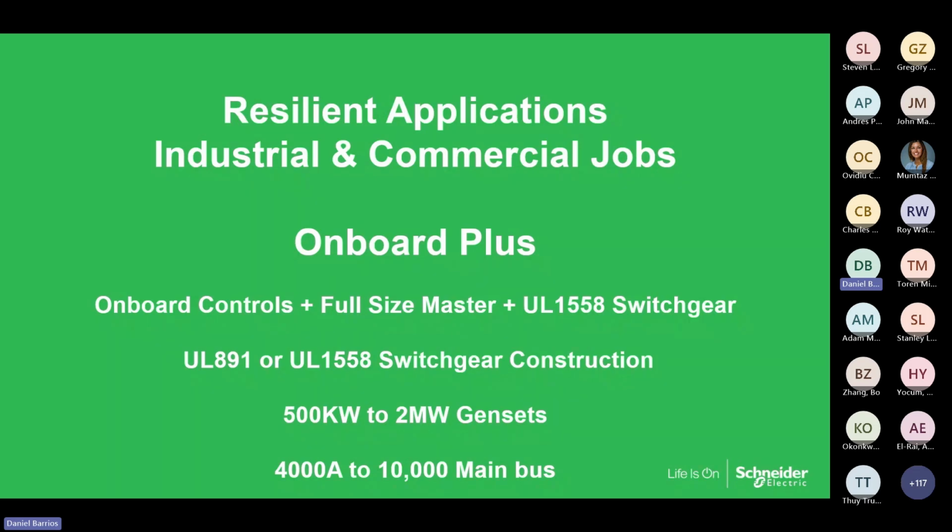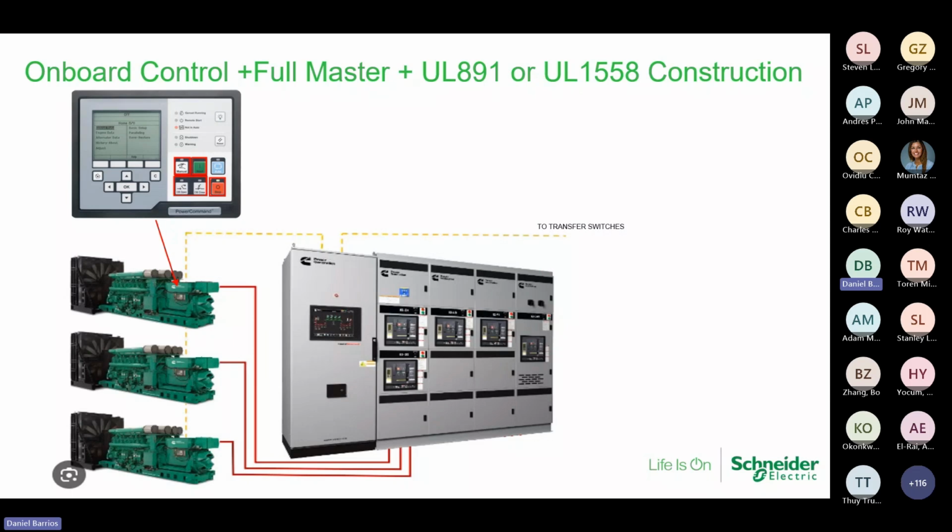That's as large as ASCO goes. How do we compensate for that? We go to the segmented bus sections where we have 10,000 amp on each section, and therefore we can put the number of generators that you need into your system.